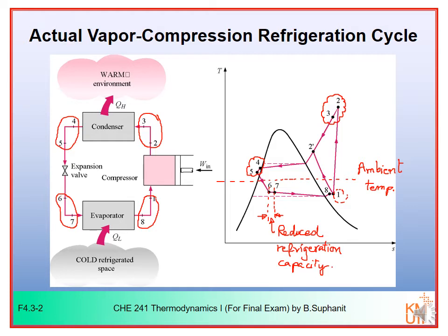With the frictional effect and heat transfer, the compressor can become an irreversible compressor. If the frictional effect dominates during the compression process, it will follow path 1 2 with an increase in entropy. So you have positive delta S, an increase in entropy 1 2.